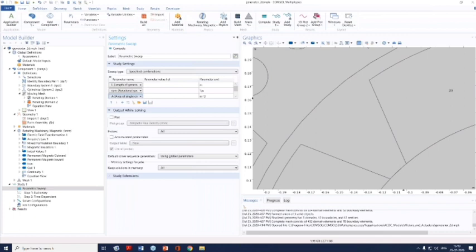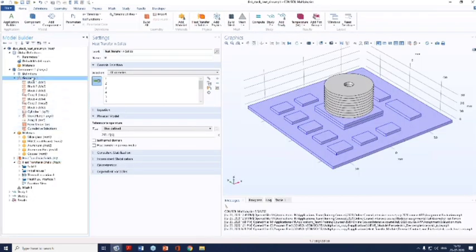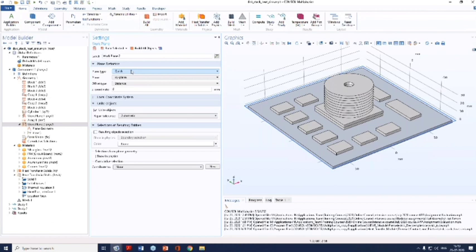If you mean to say what are the different options available, first of all, you can have different planes, you can have face parallel, similarly you can have edge parallel, edge with some angle, then you can have circle perpendicular also, wherein you can first of all select the circular edge, and accordingly the perpendicular surface will be selected.